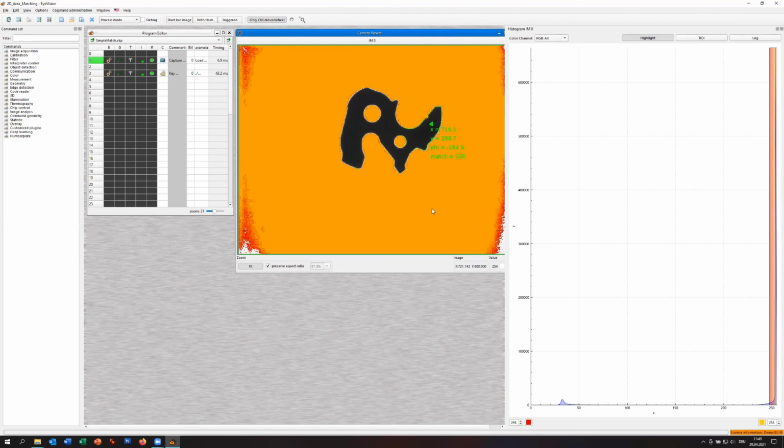But you could do the shading correction of a line directly through the incoming line. And in many cases, because you try to have a homogeneous image from left to right, it's really important to correct these lens effects. And for a line, you can do it very simply.